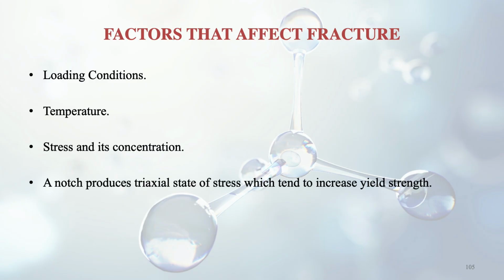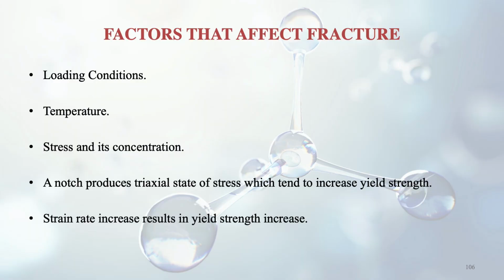A notch actually produces a triaxial state of stress, which tends to increase the yield strength. So if there is a notch, the yield strength will try to increase, making it somewhat more brittle. So the tendency of fracture will be more. The strain rate also increases the yield strength, so again the tendency will be toward a more brittle type of fracture.